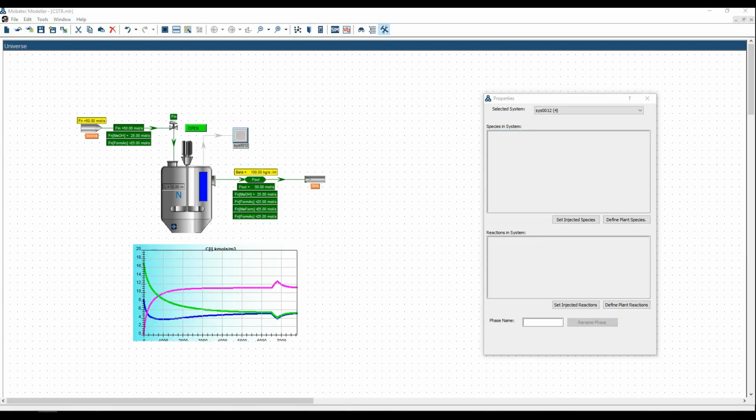Information systems can hold algebraic equations, calculating variables which are usually not related directly to the process. Having different kinds of systems and connections is the basic idea behind the Mobatec modeler methodology, so that we can distribute all our equations over the logical model objects that they belong to. Like this, our model becomes much more easy to use and much more transparent, instead of having one big system where all the equations would be stacked together. Information connections are used to send variables and parameters values from one system to another.